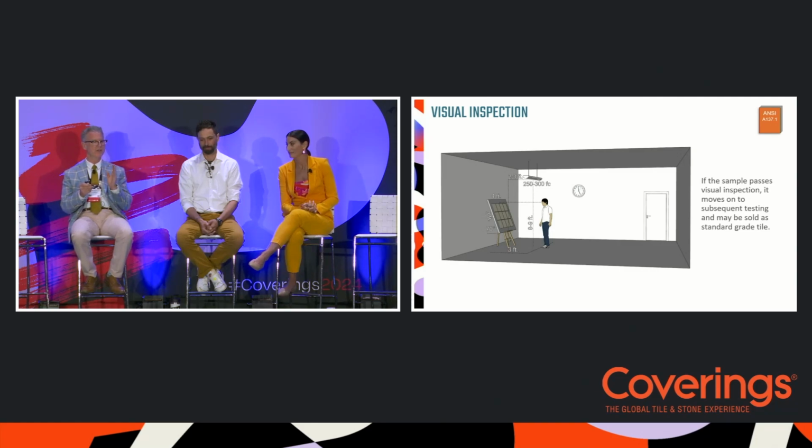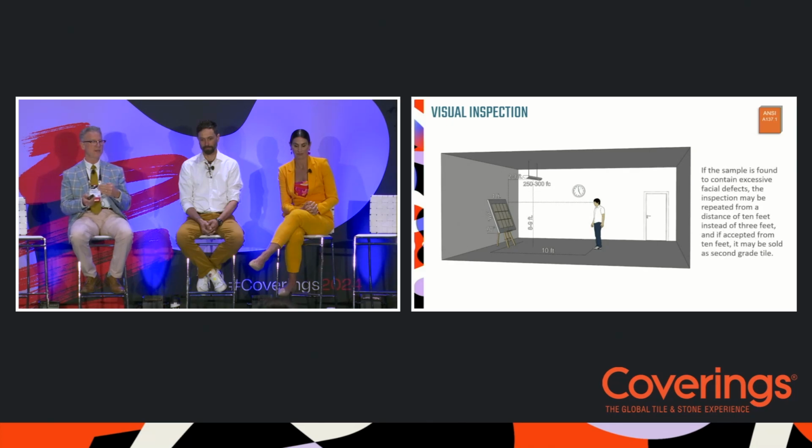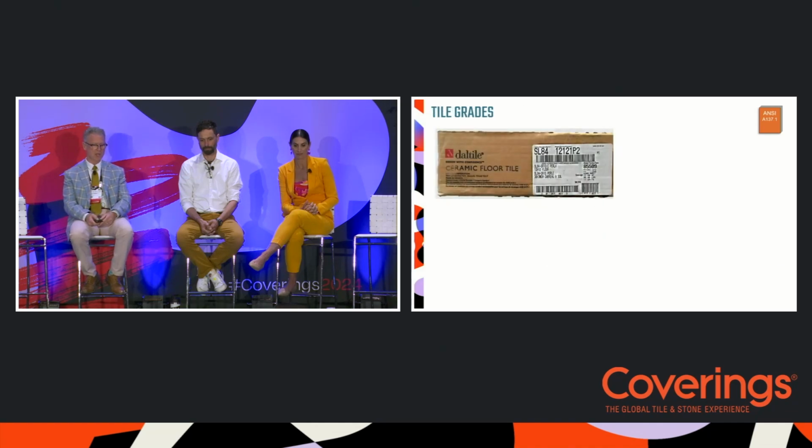Now what happens if you do notice visual defects from 3 feet? Well, the tile kind of gets a second chance, so to speak. So the individual now can back up to 10 feet and evaluate that same tile for the same set of visual criteria. Finding none, it can be sold as a second grade tile, which is going to be probably not as expensive, but also not as easy to work with. And we'll talk about some of the practical criteria.